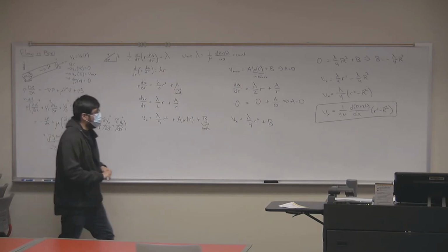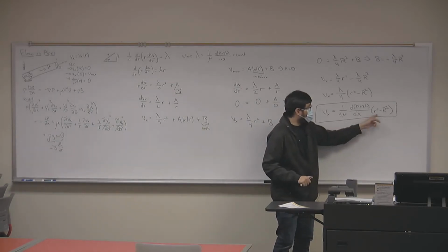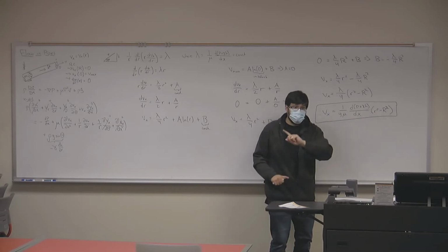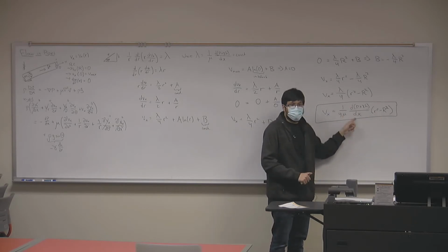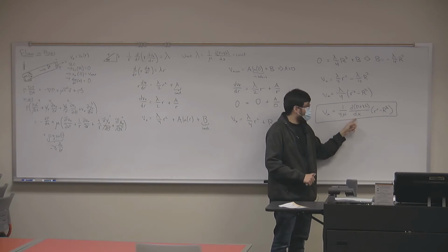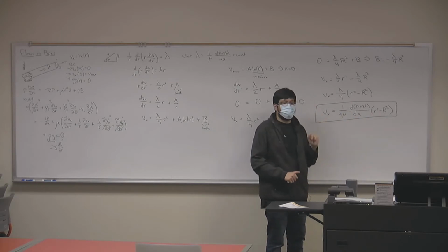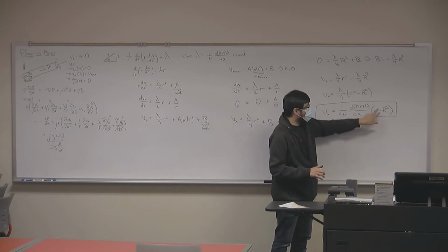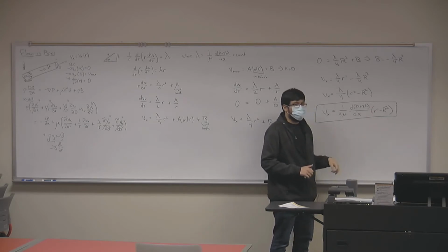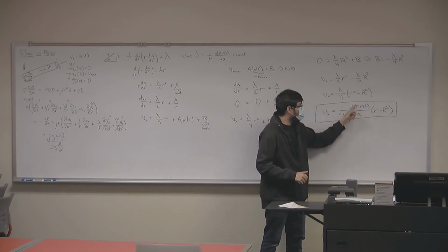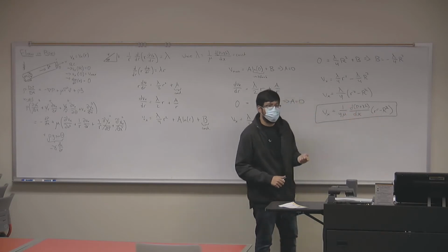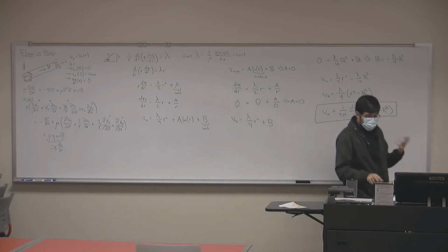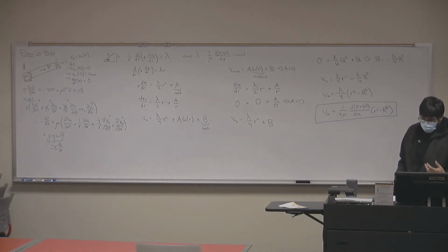Good. You may think, wait a minute, when r equals 0, you get a negative value. But remember that the pressure gradient is negative as well. So you get negative times negative, you're still going to get a positive velocity. So don't be thrown off by the fact that you'll get a negative value at the center of the pipe, because you have a negative value here, but this dp over dx is also negative, okay? So that was what I wanted to finish covering on Tuesday.